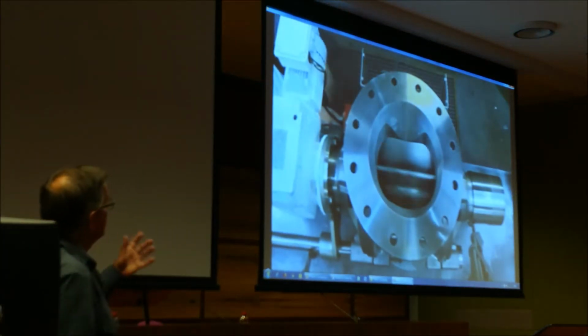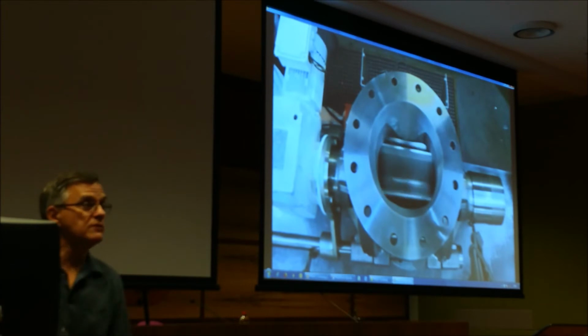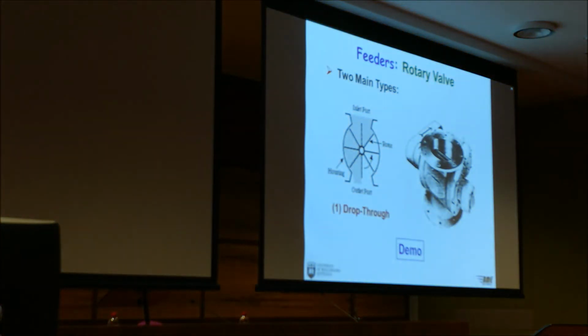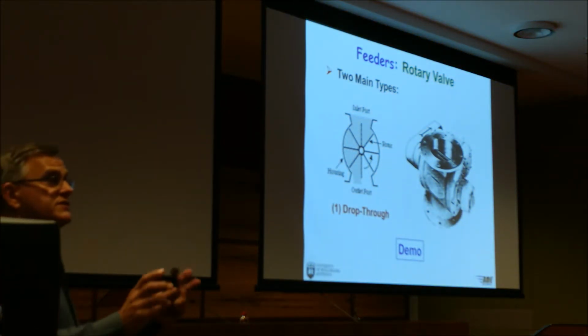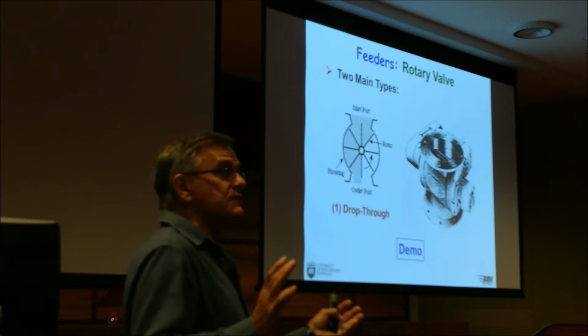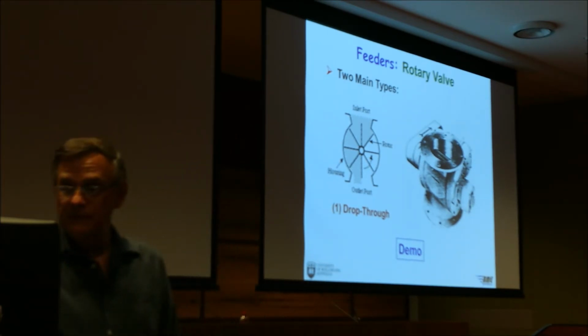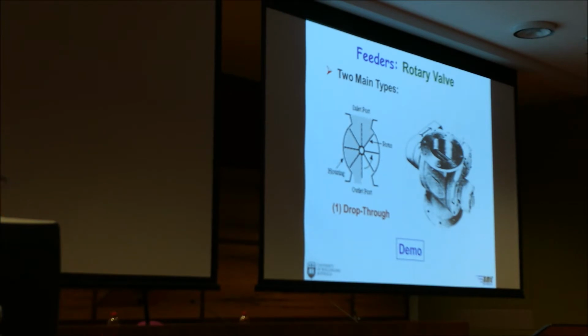And then hopefully if you assemble it properly, it'll rotate when you turn the motor on. So you need trained people to do that type of work. You can check all your seals, gaskets, everything, all your clearances are right, and then your valve should operate properly. If you don't do it properly, you'll jam something and the valve will fail.